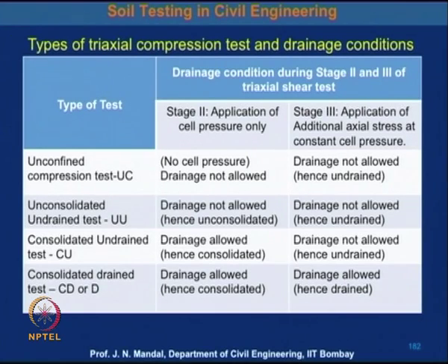So, it depends upon what the drainage condition should be during stages 2 and 3 of the triaxial shear test. First, if the type of test is the unconfined compression test, which we can call the UC test.